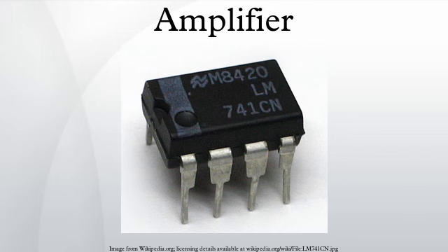The voltage signal shown is thus a larger version of the input, but has been changed in sign by the amplification. Other arrangements of amplifying device are possible, but that given is the easiest to understand and employ in practice. If the amplifying element is linear, the output is a faithful copy of the input, only larger and inverted. In practice, transistors are not linear, and the output only approximates the input. Nonlinearity from any of several sources is the origin of distortion within an amplifier.